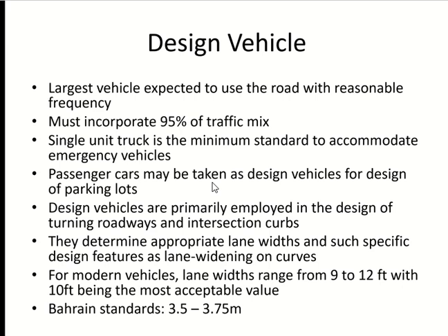Because of the cost. Just to cover one more extra percent, I will have to increase my pavement thickness. I have to increase my road space as well. It will take a lot of cost just for 1% traffic. So if the traffic expectation is very low, we ignore it and design for the remaining. Clear? Some guidelines are given.